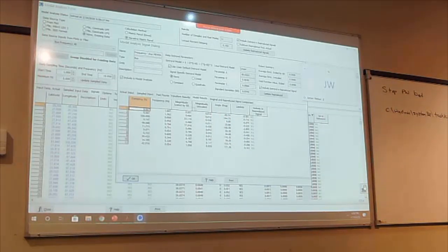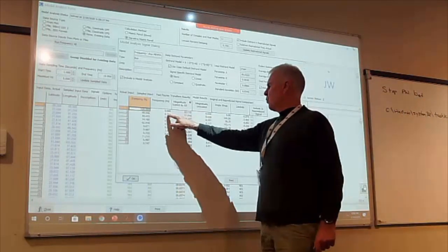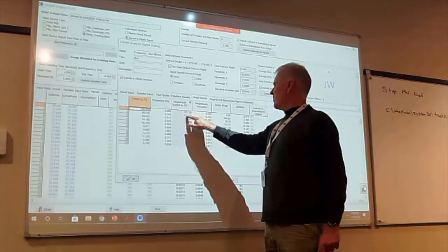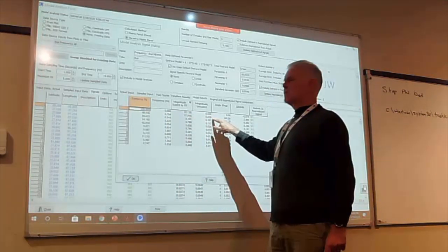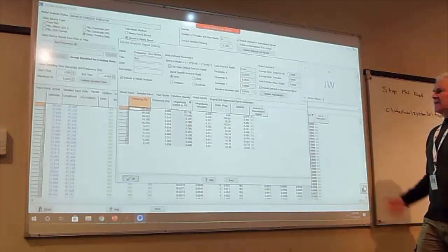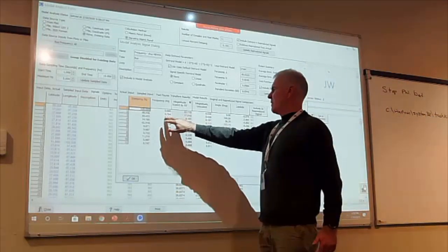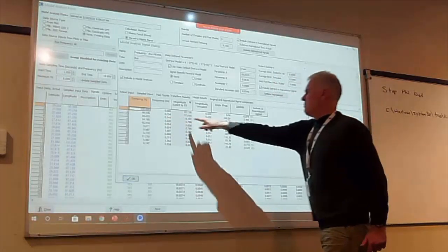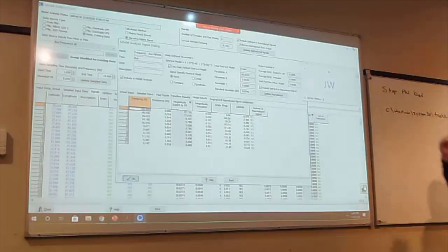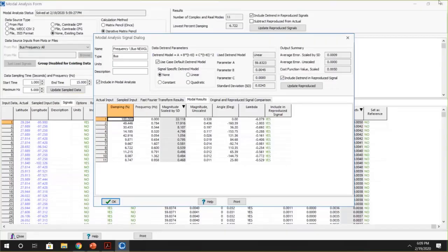And if you said, what's the damping on that signal, I would say, okay, the largest oscillatory component in that signal is at 0.8 hertz, and it's got a value of unscaled 0.436. And then I'd say, and there's another component that's at 0.3 hertz, and it's got a magnitude here. And then I show you the real and the reproduced to quantify it, so that you feel good about my results. You feel like, yeah, this is right. I'm demonstrating that we've matched pretty well.